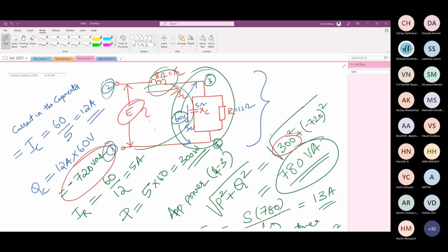No. See, this is the power triangle approach. Okay, what we are doing here is, I'll tell you. See, here this is my S, this is my P, this is my Q. Now this is the theta. Now if I compensate partially the reactive power, then which will give me a lower Q, so this is Q1, this is Q2, this is Q1 plus Q2.